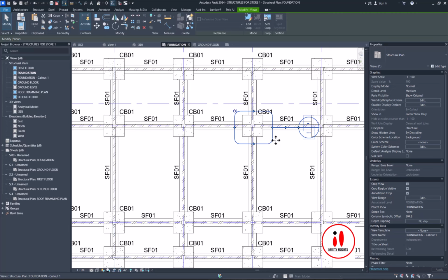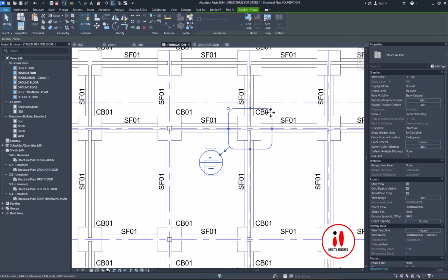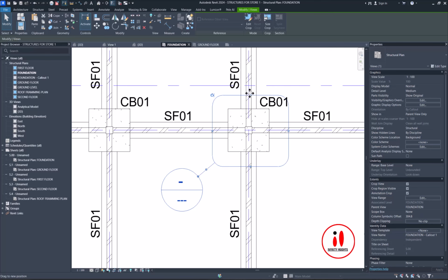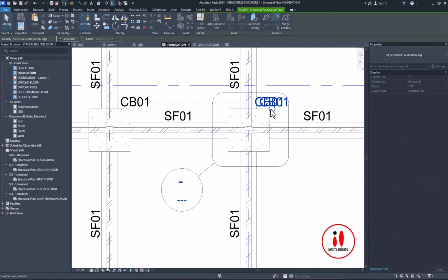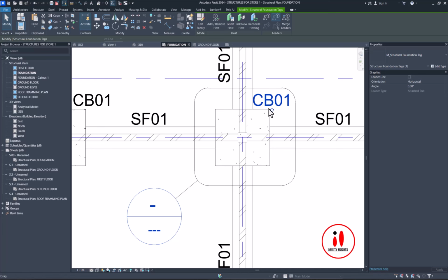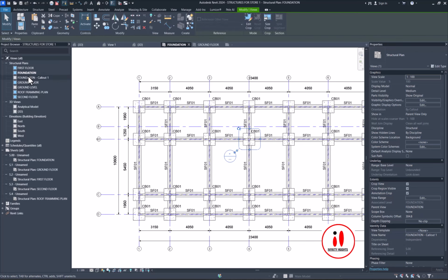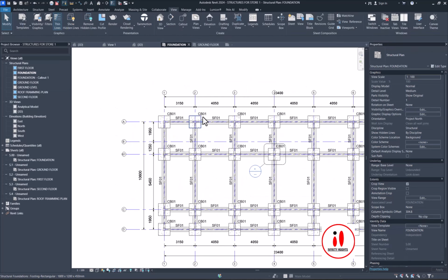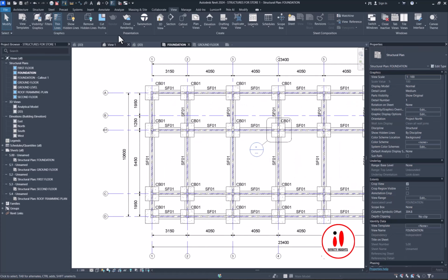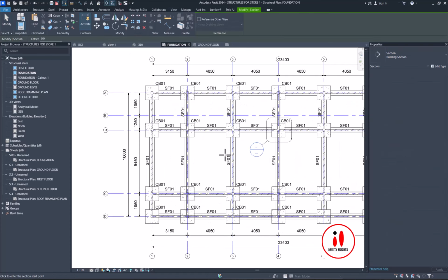Then I'll click on the call out again, then I'll click on the node. Then I have the chance to drag it where I want. So what I do is I don't interfere with my drawings, like my tag, my color. I don't put lines on it because for communication purpose, you get it. So you always have to find a way to put your tags so that they will not interfere with the lines that you are communicating. You get it? So now we have our call out here, and the call out is going to come under the foundation. Also, you can take a section for the depth of the foundation.